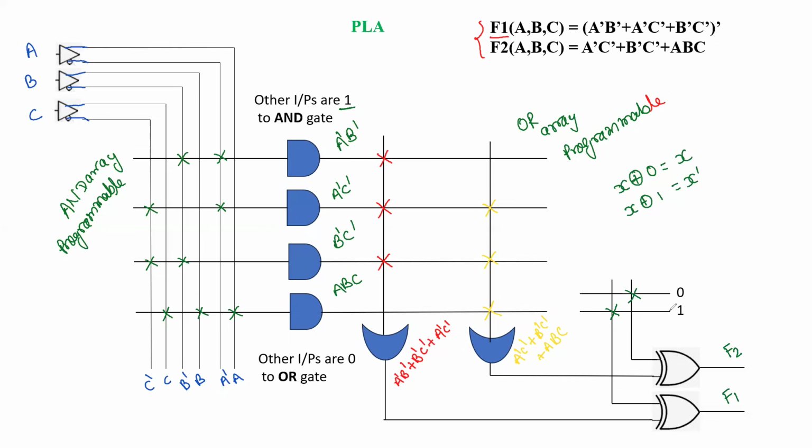So as per the given function, we can utilize the opportunities to choose how many variables are there and how many AND gates we are going to get, that is, the product terms. In our programmable array, whatever ports are open, that input is considered as 0, since in an OR gate, if any one input is high, the output will be high.